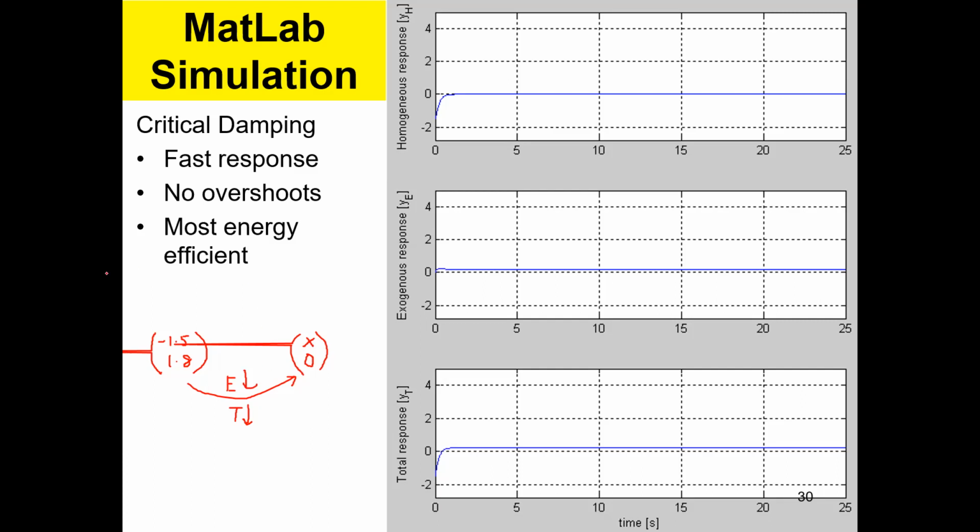If you critically damp, you get the minimum energy condition. So therefore, there are a lot of control systems where you are supposed to critically damp the poles, and you do a lot of things to bring the poles together. If you have two poles, you have to bring both poles to one place. If you have 5, 6 poles, look at the most dominant poles, 2 poles, and bring them together, right?